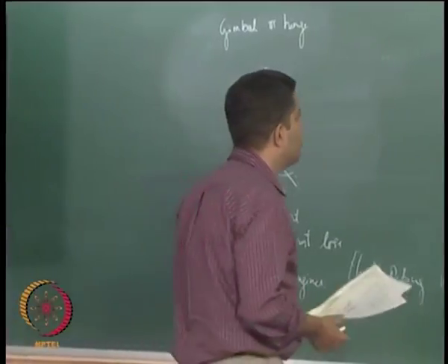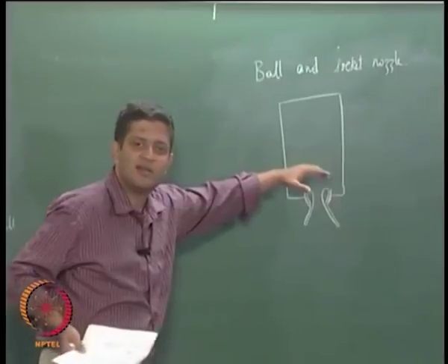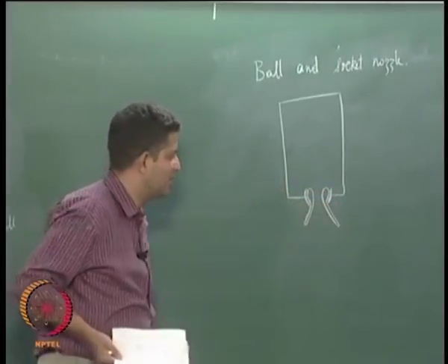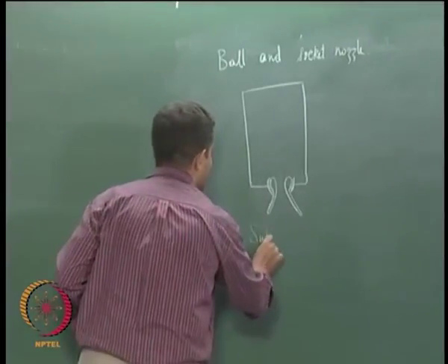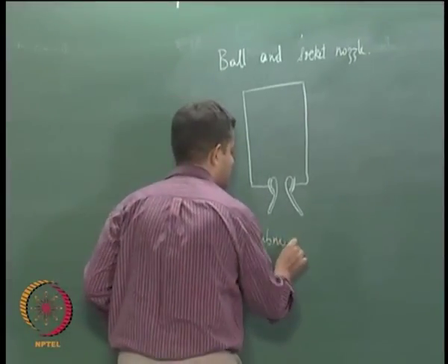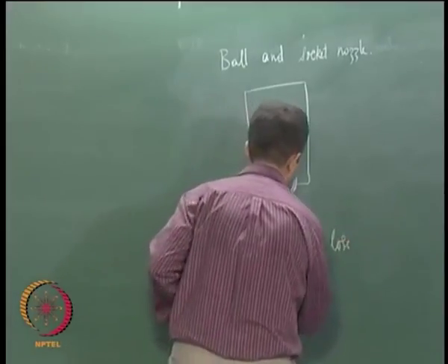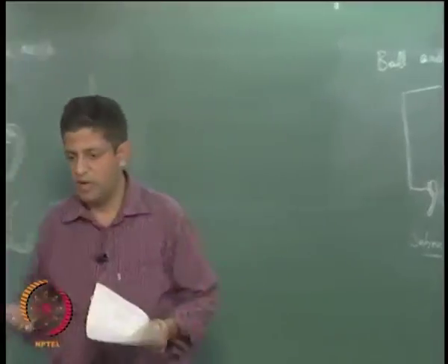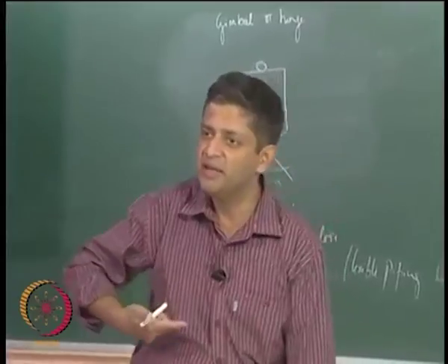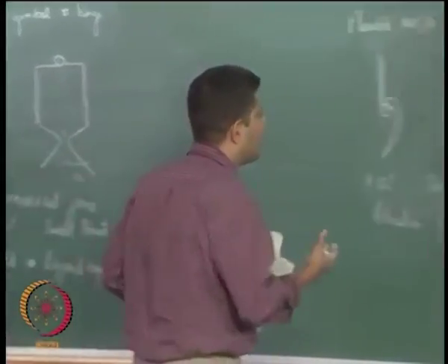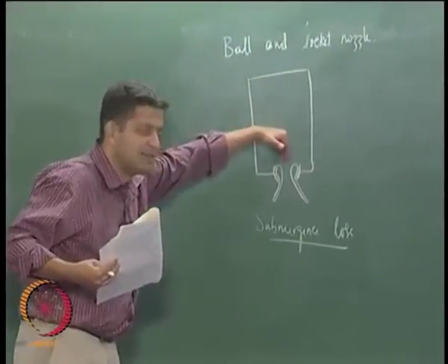Now, in both these methods, the nozzle in some sense is submerged inside the motor, and this leads to something known as submergence loss. Primarily, if you look at the gases coming out, you would also have propellant stored in this direction. If it is coming in this direction, it is a lot easier.